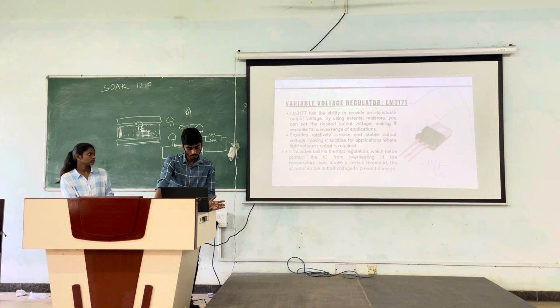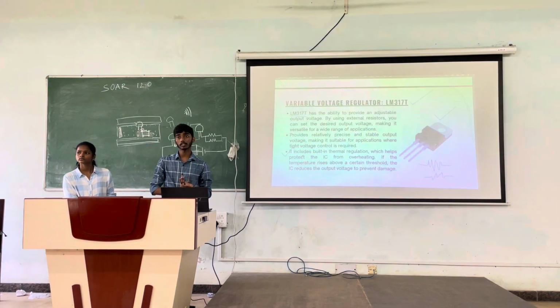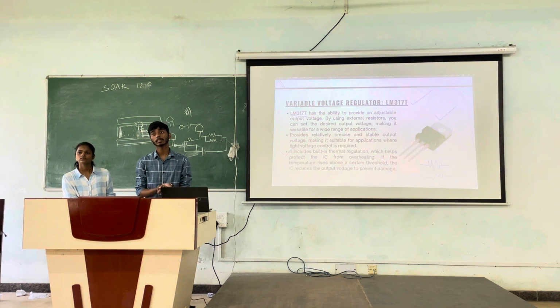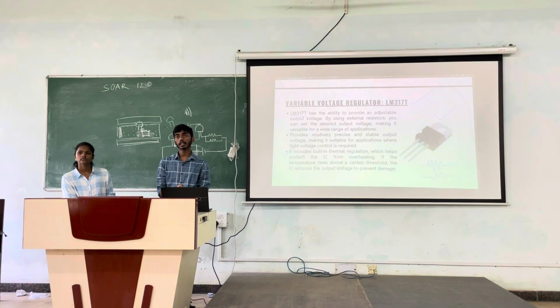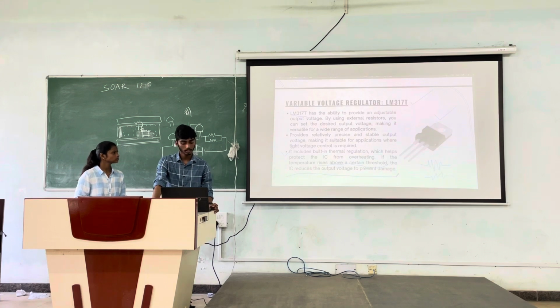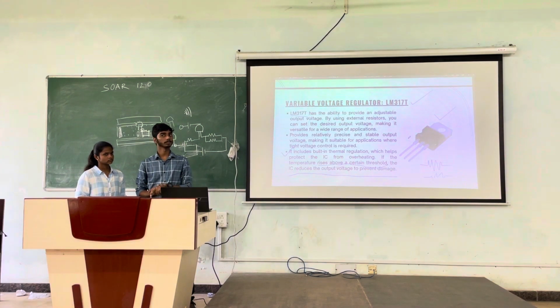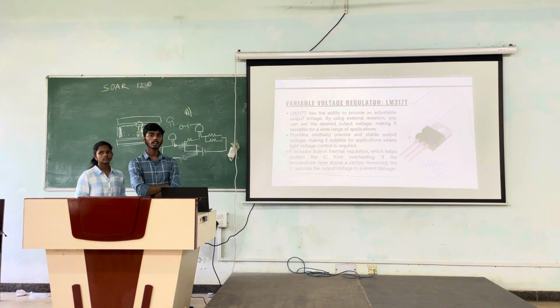And this point is a bit important. It includes built-in thermal regulation. If the IC gets heated, like if we draw so much current that it gets heated, this IC will automatically drop its output voltage in order to cool down. So it has a built-in feature: if the temperature rises above a certain threshold, the IC reduces the output voltage to prevent damage. Do you have any doubt in these three points? Any doubt? No, nothing.